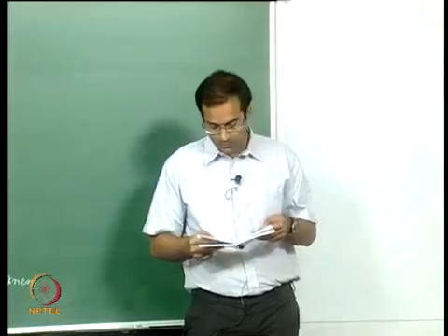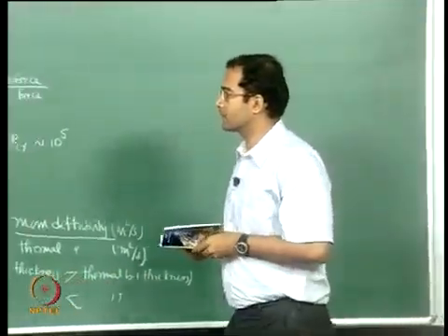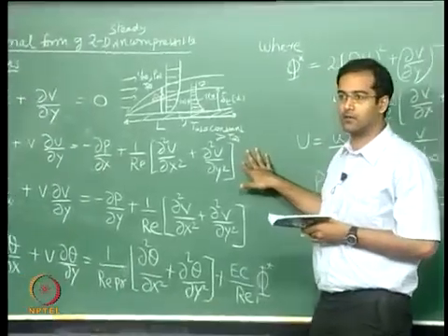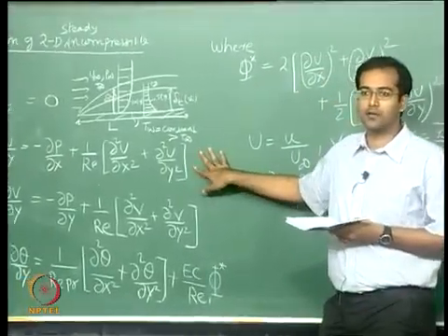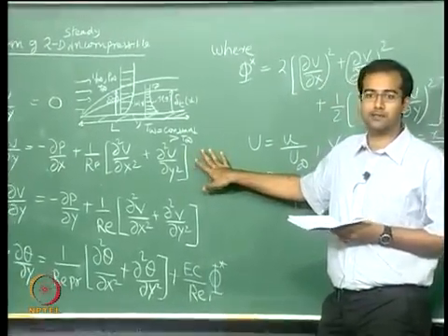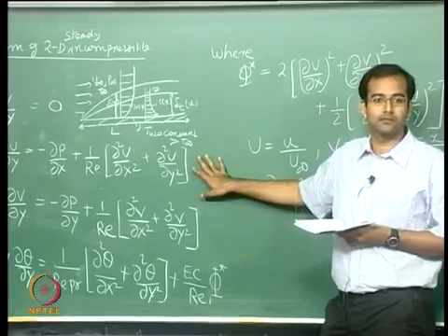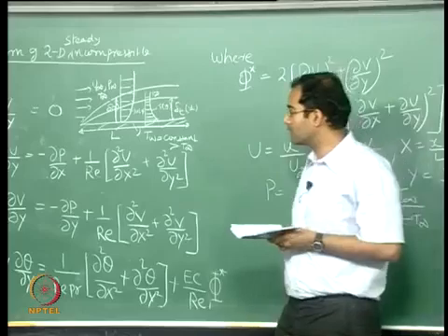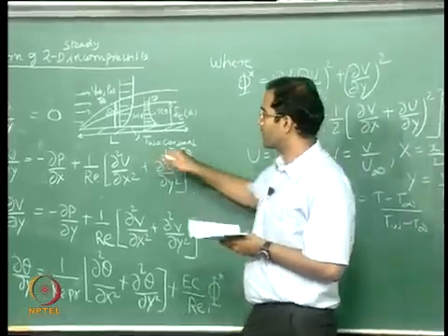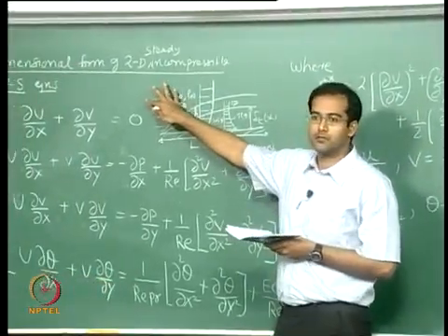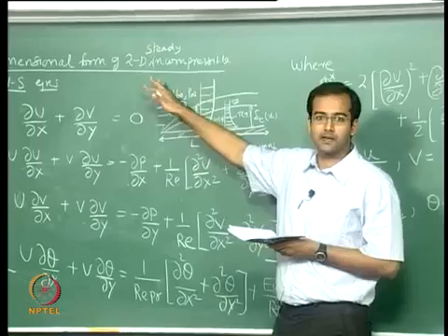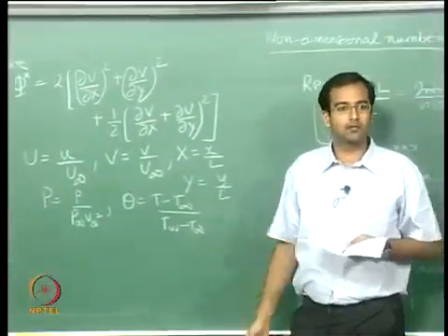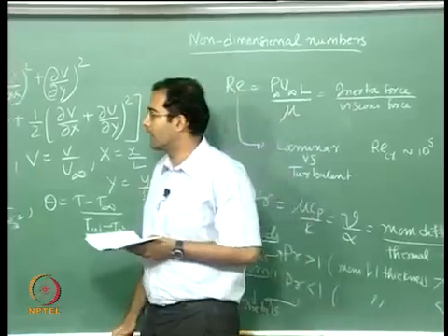Now when you go to flows, suppose you have a body force here, which we have not included now. You can have buoyancy which is driving the flow, so that is the natural convection. So even though you don't have forced convection, you don't have a velocity which you supply by means of an external blower or pump, you can have natural convection happening due to the buoyancy forces.